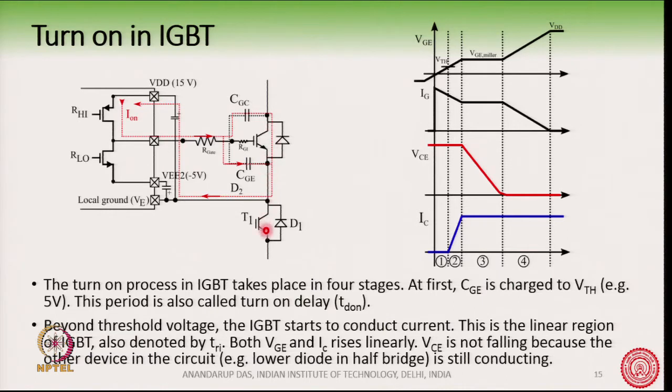You can see here there are two IGBTs connected following the half bridge structure, which we have used heavily in this course. I have tried to use such a circuit, but the analysis is also valid for other types of circuits. Now, the DC link, for example, is present here, and you will also have the load current flowing out here. So, this is the half bridge structure.